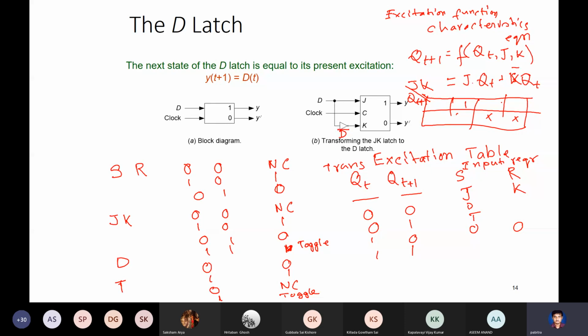Ideally, we want the clock pulse to be thin enough so that only one change happens. It is not sensitive to change within that clock pulse, only one change happens in a clock pulse, and the clock pulse is wide enough to allow for that change. The combinatorial circuit delay should be less than that. It should take into account the delay.